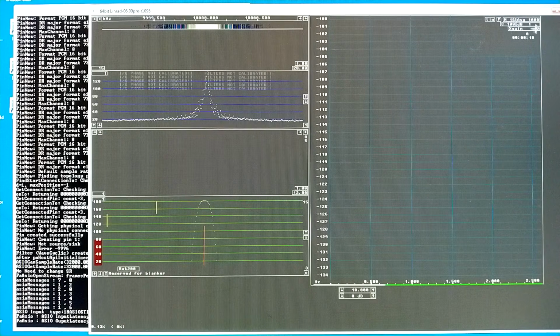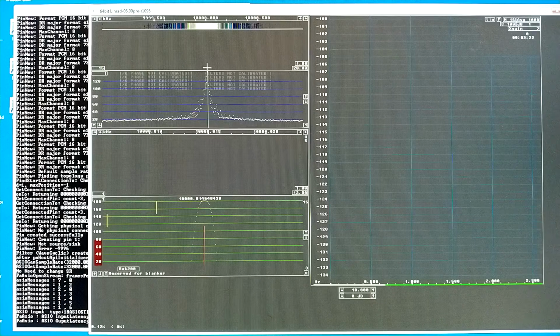So what I can do in Linrad is to set the linear mode for displaying the phase noise, and then I select the suitable X gain, 7 in this case, that limits the range to 2.6 Hz, and it starts at 0.67 or something like that. The starting point is given by the Fourier transform size, which is in this case 16. And I can start collecting the phase noise by clicking on the signal here.